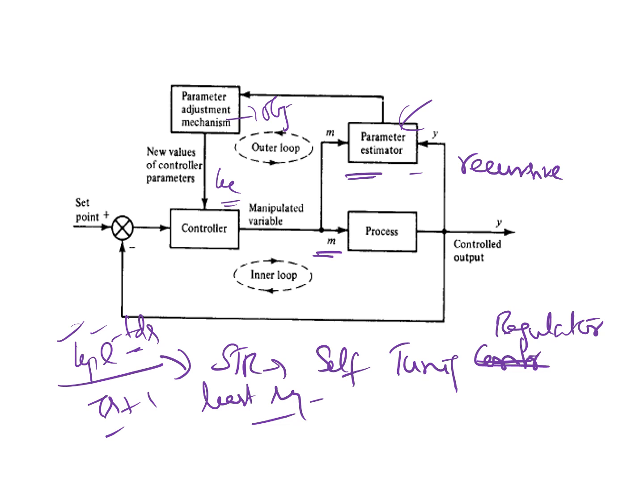Okay, so far we have seen adaptive controllers. So we have seen why do we need adaptive controller for a chemical process, because of its nature of non-stationary and non-linear. So for that we have to address that. How do we do that? By imposing an objective function. That objective function may be phase margin or gain margin or ISE or IAE or ITAE or overshoot or a less rise time or a 1 by 4 decay ratio. It depends on the user. Okay, so create an objective function which should follow that criteria.